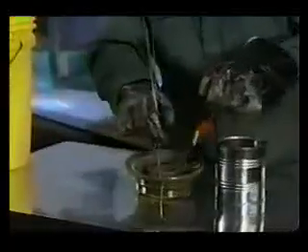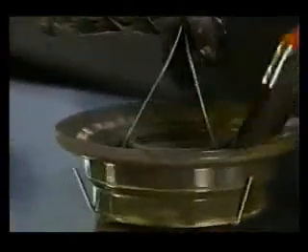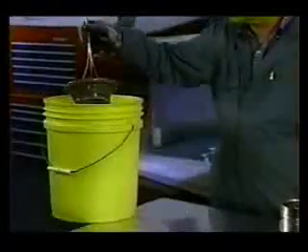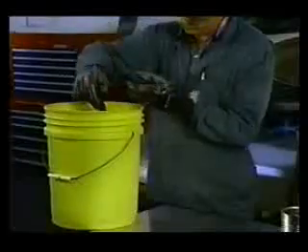After cleaning, a chemical conversion coating such as chromic acid or Alodine should be applied to inhibit corrosion and provide a suitable surface for painting. Mix the conversion coating according to the manufacturer's instructions. Apply to the surface with a stiff bristle or paintbrush. Quickly rinse the area with water to neutralize the solution and stop the reaction process. Repaint the treated area with the paint mentioned in the manufacturer's specifications. This should include an epoxy primer and top coat system.